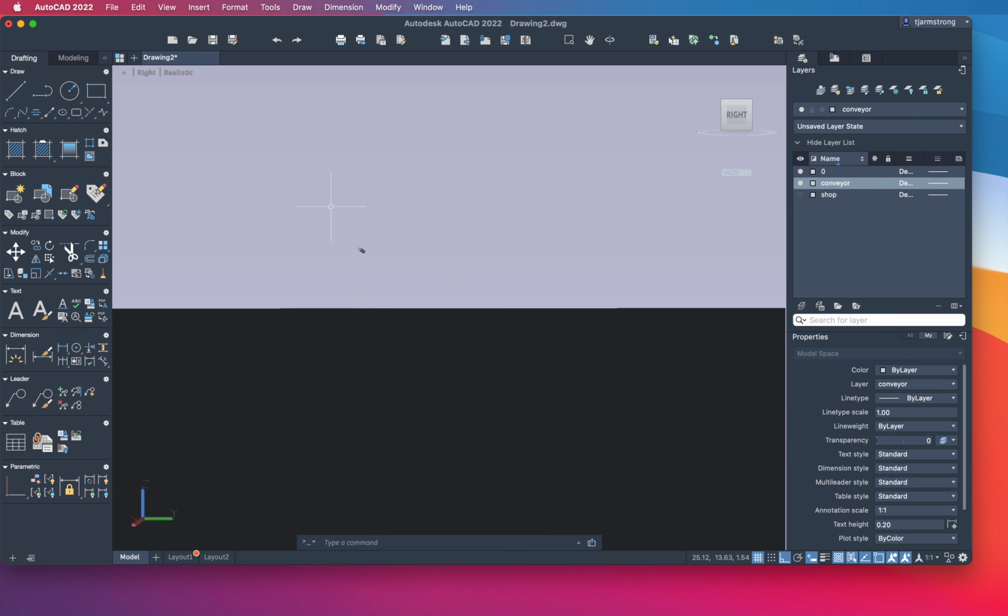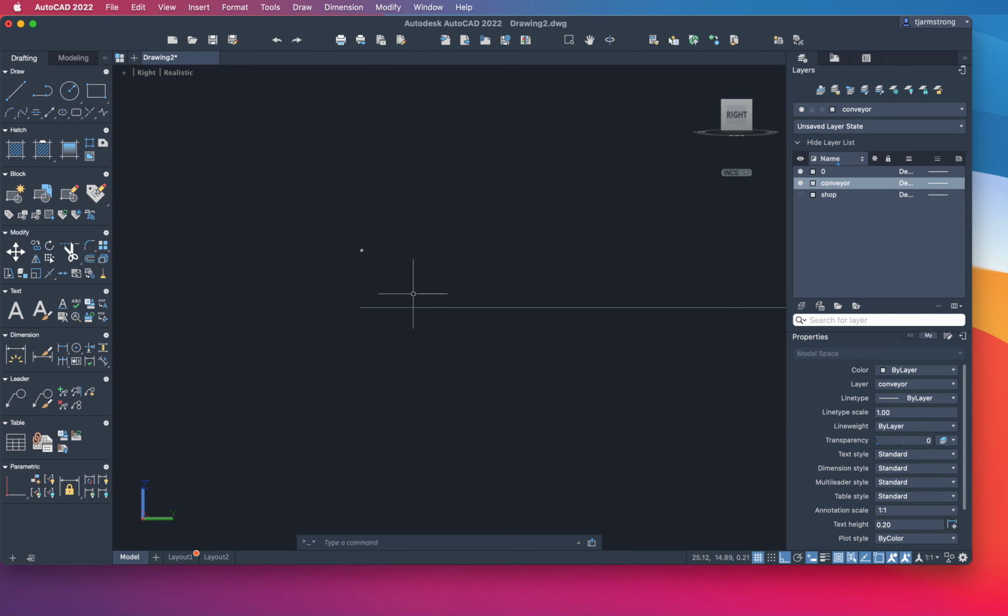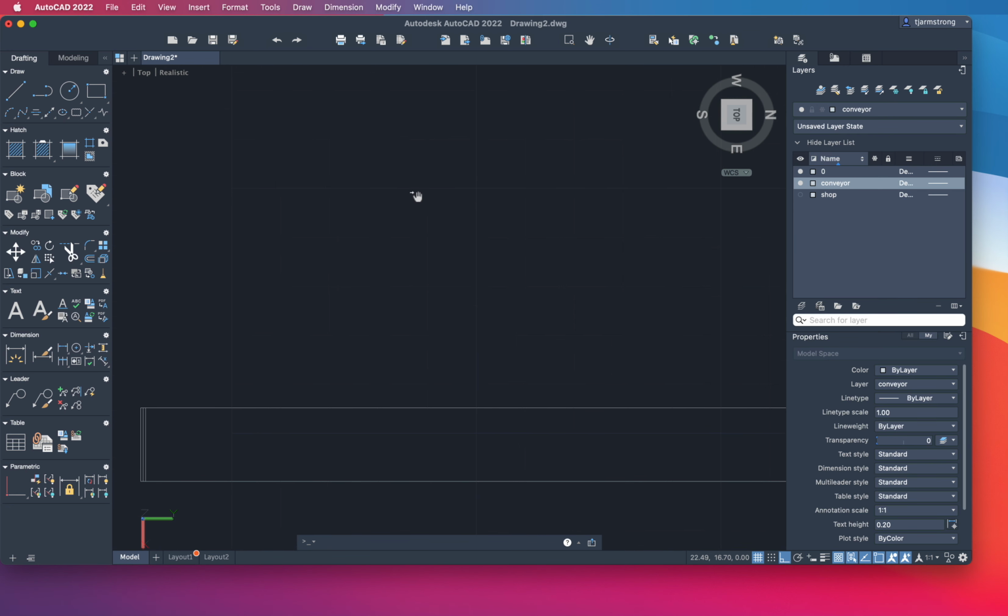I'm looking at this in a perspective view. So let's come back over here to the menu in the upper left corner, and we'll come down here and show the parallel view. Okay, that looks good. You can see that this is now right above the end of this, and we'll verify that even more certainly in just a sec. But let's look at it from a top view, and that looks pretty good as well. I'll zoom in a little bit so you can see. So it looks like we got that lined up very well.